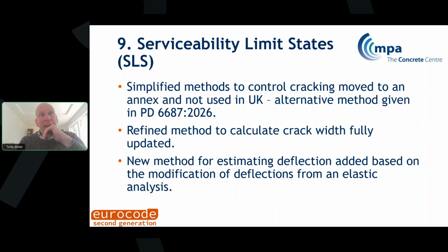And the other real benefit, again reflecting the way that engineers work now, is there's a new method for estimating deflection based on deflections from an elastic analysis. So we can take a deflection out of our model and apply a factor to it, much like ACI do, and get a better estimation of the real deflection.